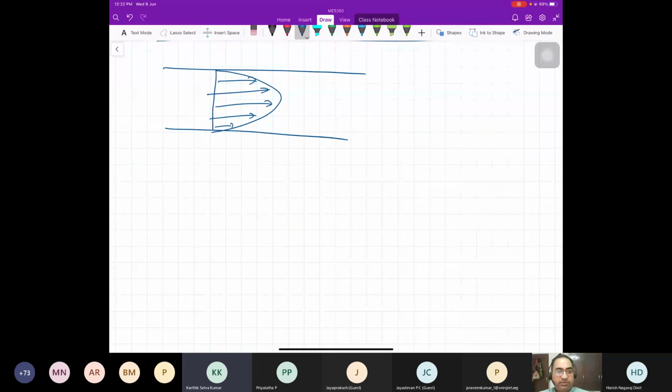Whether it becomes turbulent or not is a big question. Okay, we'll come to that after your question. It need not be turbulent. I know that this simple wave-like solution will not be there anymore. That much I know. What it will go into, I don't know. For example, you could have nice, elegant vortex shedding, right? You have a nice smooth flow, and then in Karman vortex shedding you get these vortices, positive and negative. Those vortices need not be turbulent. Those are still in the laminar regime.